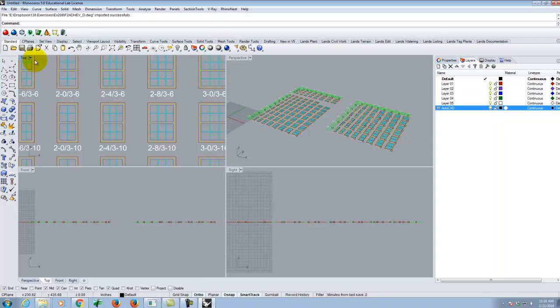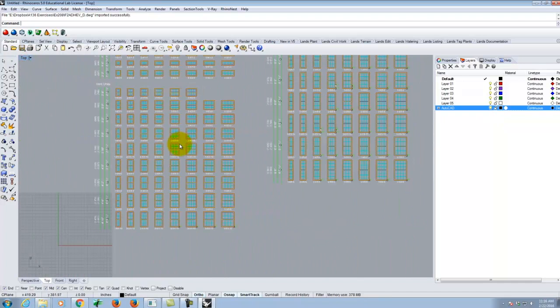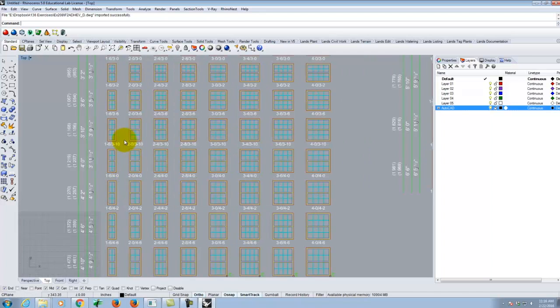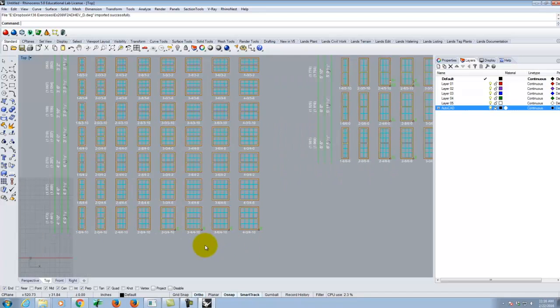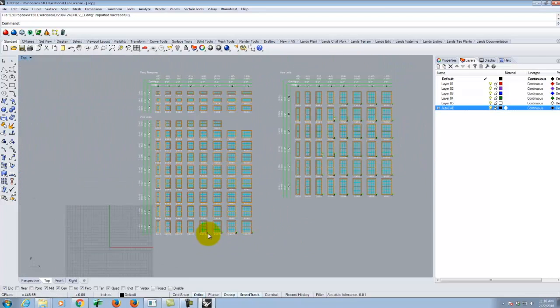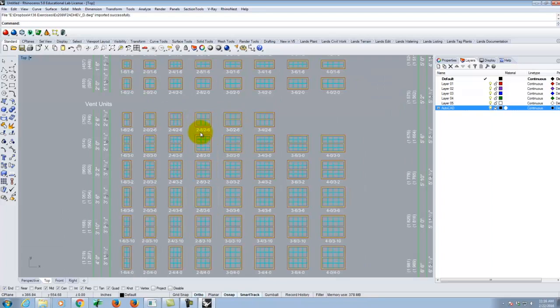Okay, so now let's take a look at these windows. I'm going to pick some size window to do. So let's see here. I can look at the general sizes. These are listed as widths followed by heights. So 2.8, 2.6 would be 2'8" wide by 2'6" tall.